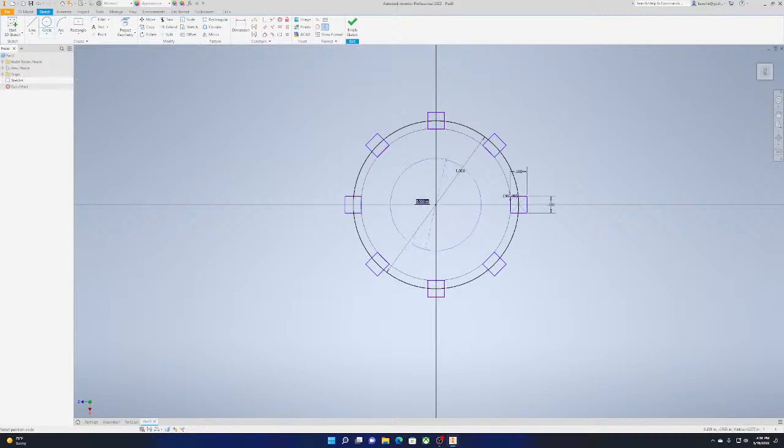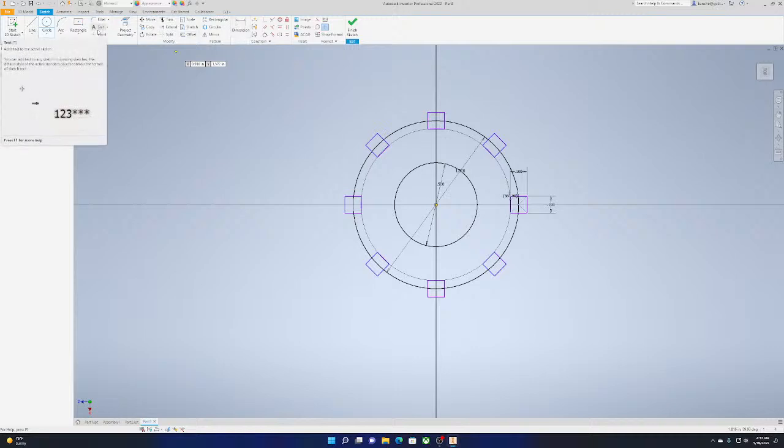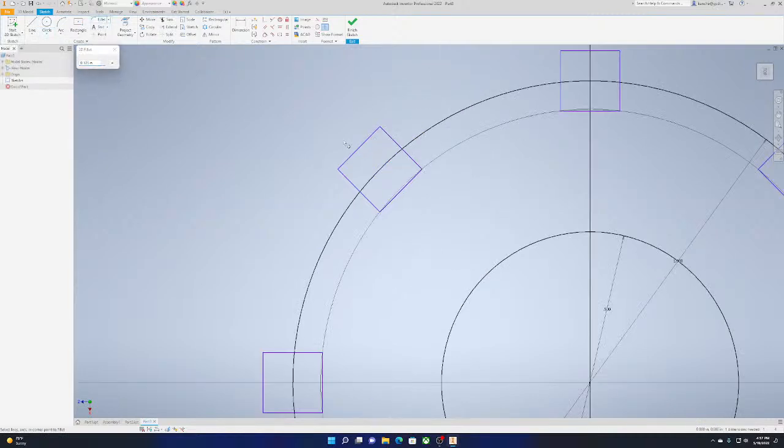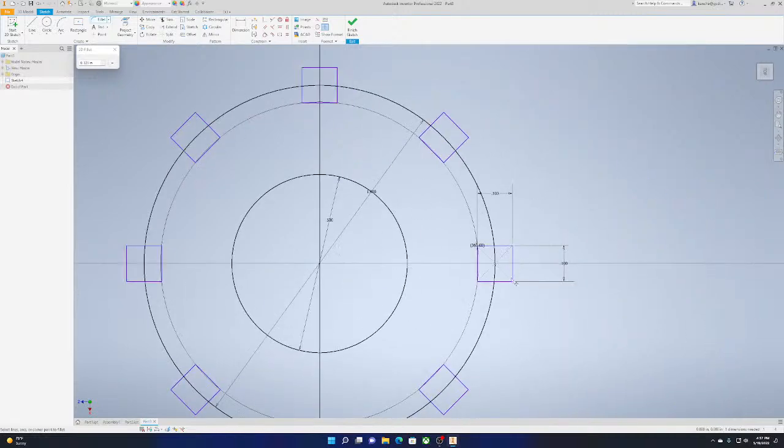I can do another circle on the inside. We'll do 0.5. And then I'll try something else. You can fillet with your sketch tool if you want a 2D rounded edge. Like, can I do that here? No? Guess not, it's not going to let me do it here. But you can do it. It's just really weird when you do it. It's not weird, it's just rounding the edge and then you extrude from it, instead of rounding an edge that has 3 facing points.